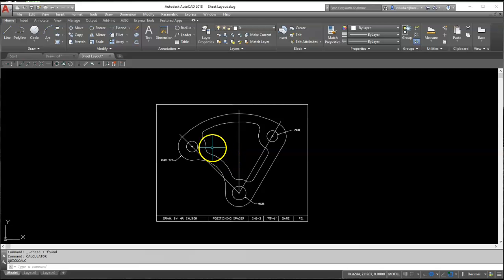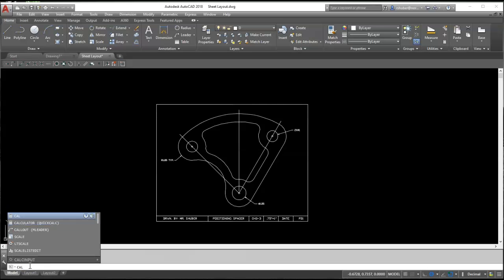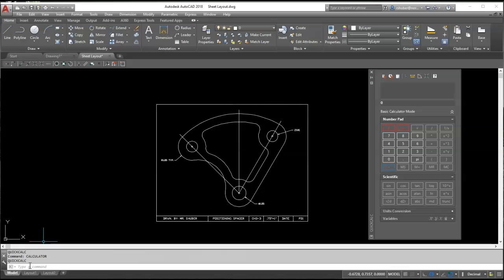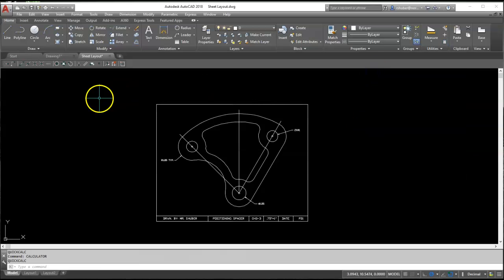Alright, the next thing that we want to do is put the arc center line in here. And that has a radius of 6 inches, but you have to understand that we scaled this down to 0.75. So we have to figure out what 3/4 of 6 inches is. All you have to do is simply take 0.75 times 6. And I wanted to show you, you could type in the command line a calculator here, and AutoCAD does have a calculator. So let's type in 0.75 times 6. That gives us 4.5. So that's actually not too bad of a radius for us to key in.